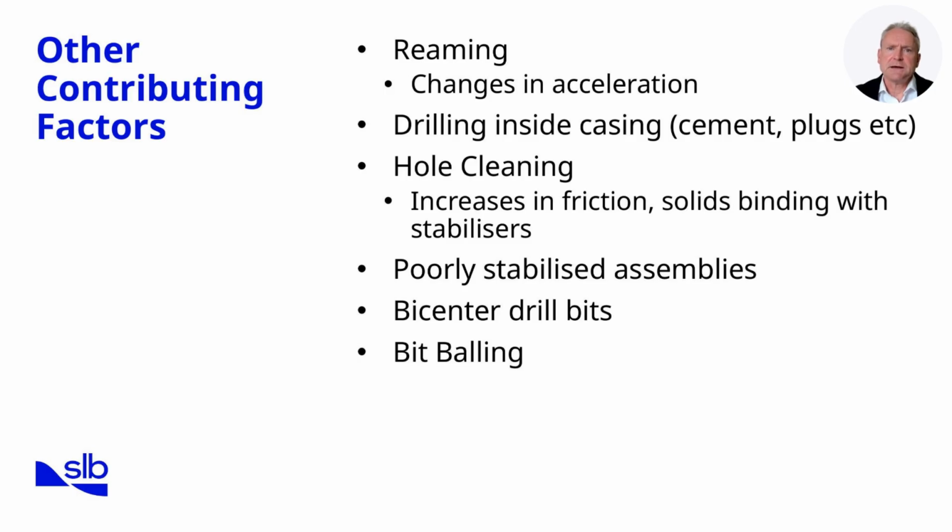Poorly stabilized assemblies further exacerbate this by allowing lateral movement of the string. Bi-center drill bits, which are inherently unbalanced in geometry, also increase vibration risk. Finally, bit balling is a classic source of dysfunction. When formation material packs around the cutters, the bit's cutting action is disrupted, leading to stick slip and axial shocks.